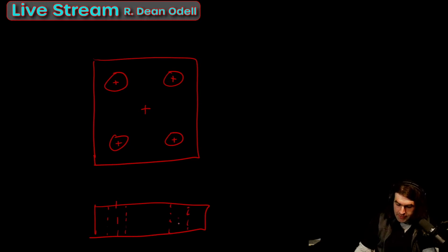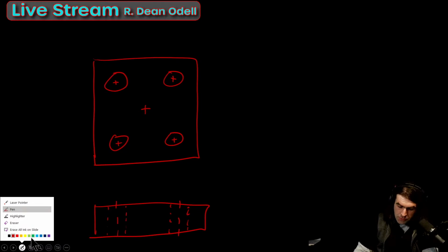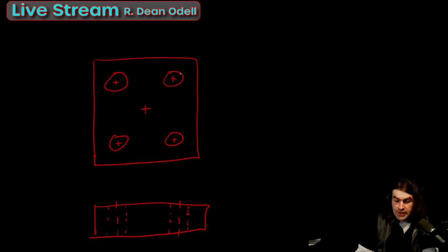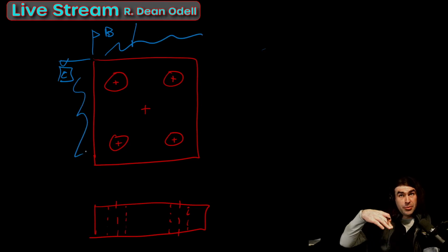And why would we want to make these holes a datum, right? What would possess us to make things more complicated than they need to be? Well, it comes up, say these 4 holes, you have fasteners or something going through it, and the outside of the part just mates to air, like a light switch cover, right? Only the 2 holes really matter, and everything else doesn't matter hardly at all. So in that case, it wouldn't make sense to make these edges datums, right? Because they don't mate to anything. If there's just air out here, we don't need to be measuring from them.